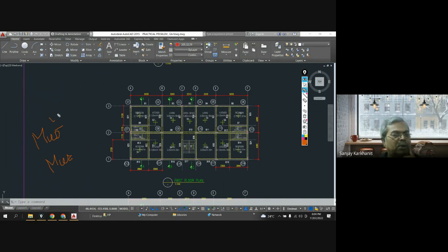See, this will be as per your design, but if you are getting for the same size more MUR in one case, and in another case you are getting less MUR, that is the capacity of that column to carry the moment. So that is MUR, moment of resistance. That is the capacity of the column and reinforcement that you are providing. And design moment is the outcome of your loading, spanning, arrangement, and all that.